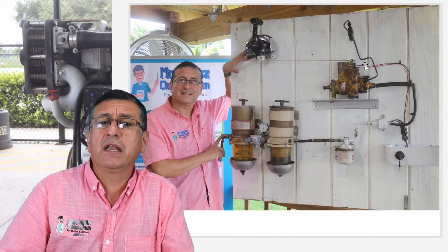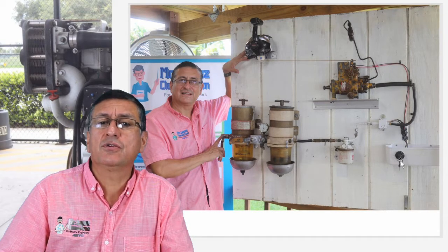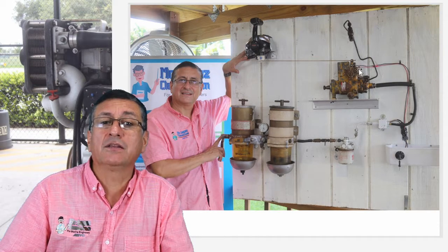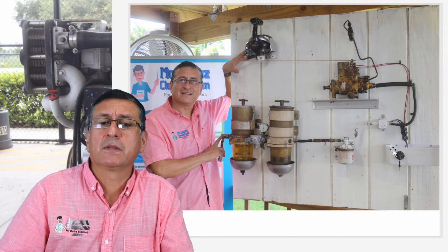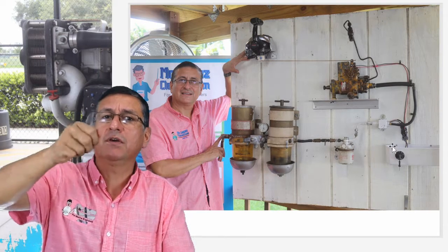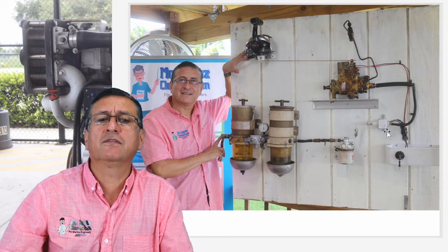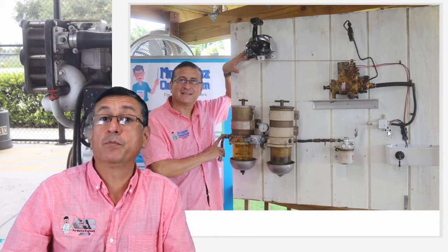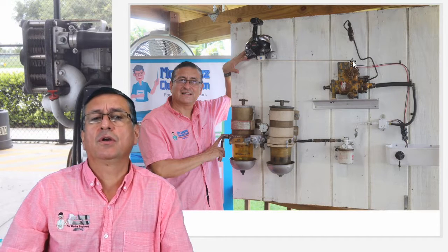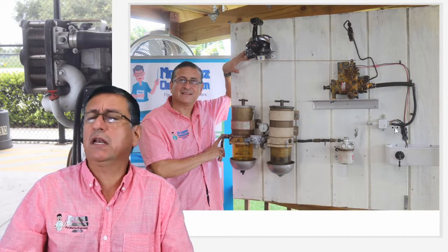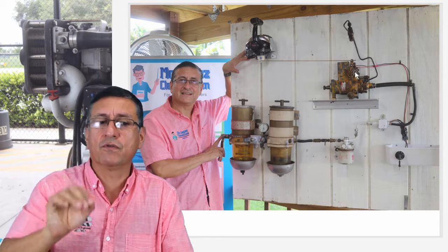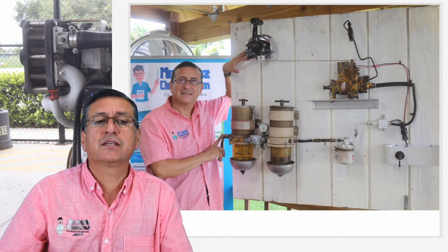Of course, in this pump, the fluid enters here only if the solenoid is open. The solenoid opens and closes through those cables, and those cables are connected with the ignition switch, exactly the same as the transfer pump. Both of them, the transfer pump and the solenoid at the input of the fuel injection pump, are controlled by the ignition switch. When you activate the first position on the ignition switch, you activate the fuel transfer pump, the low pressure pump, and the solenoid of the fuel injection pump. Both of them. Right now we are going to talk about each of those elements in the next coming video.